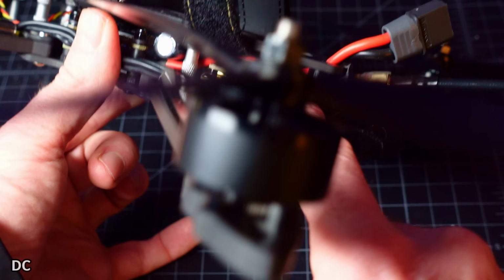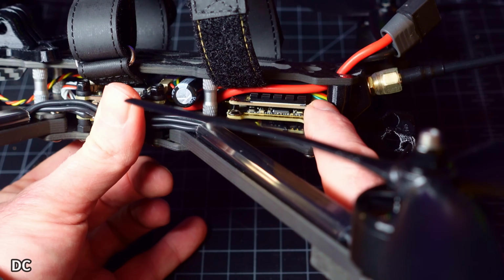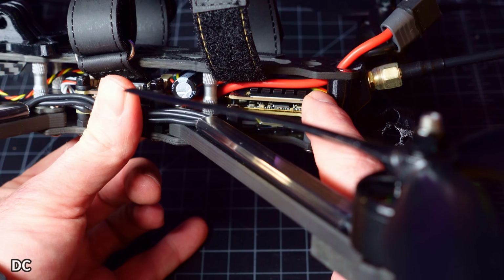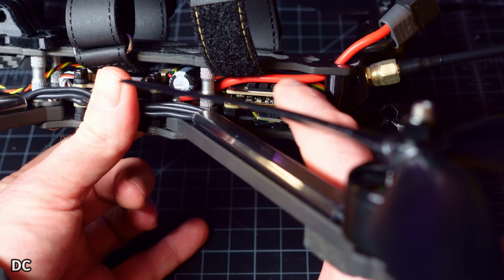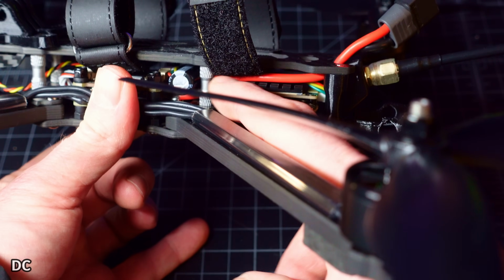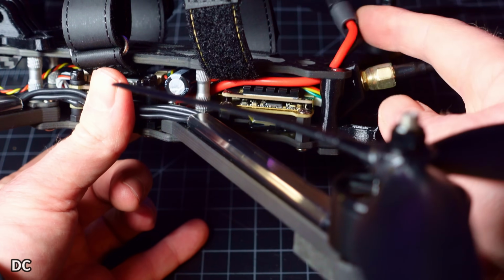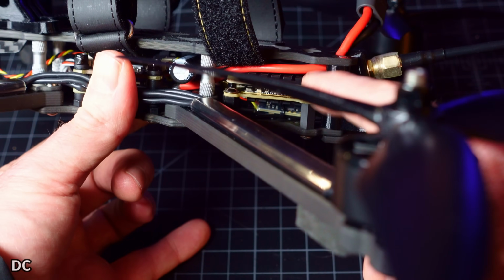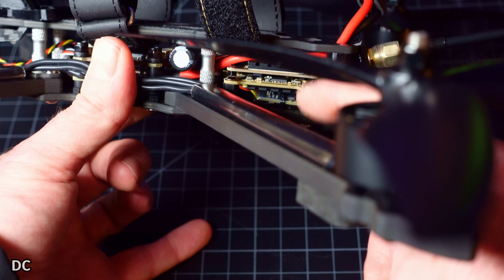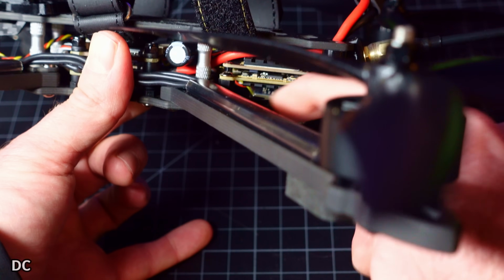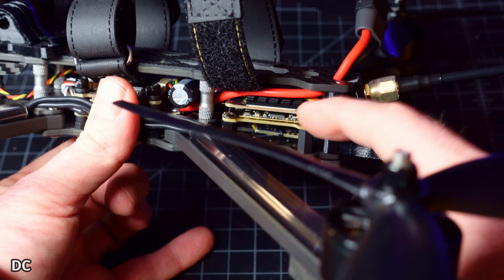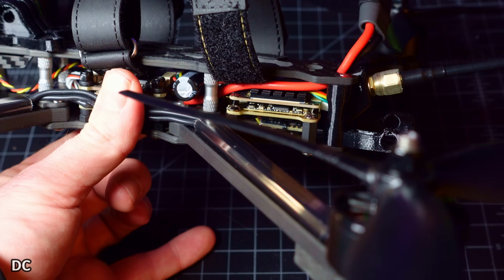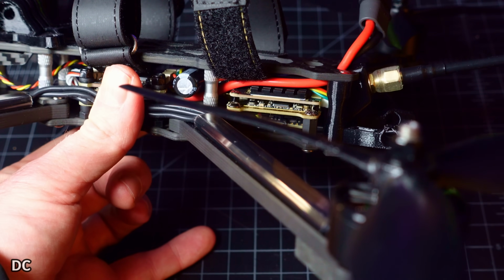So right here you can see where these wires come up. This is the yellow cable, here is the signal wire coming up from the VTX. And mine actually does happen to be coming straight by this power line, right straight to the flight controller coming off the battery. So if you move that video signal as far away, maybe run it underneath the VTX away from the power source to the battery, you're going to get a much cleaner signal back to your goggles. There's going to be way less interference.